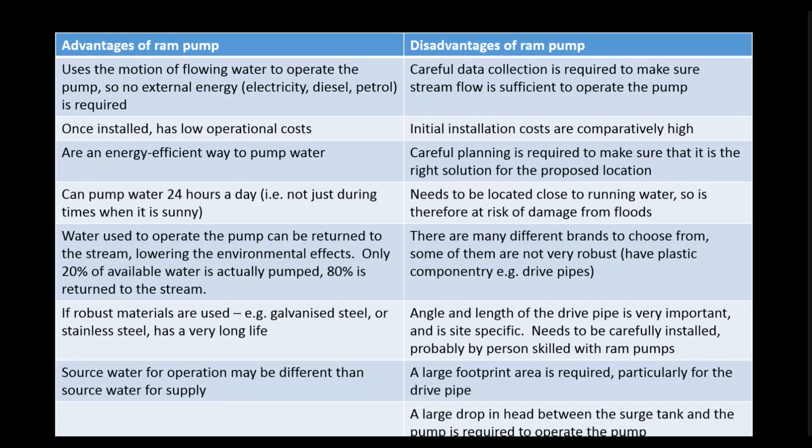The things that you have to be mindful of include that you need to have really careful data collection to make sure that the stream flow is sufficient to operate the pump, because if you've got a stream that either dries up or reduces its flow at certain times of the year, then you are going to have a reduced pump volume, and you're not going to get as much water pumping into the water tanks as you hoped for.